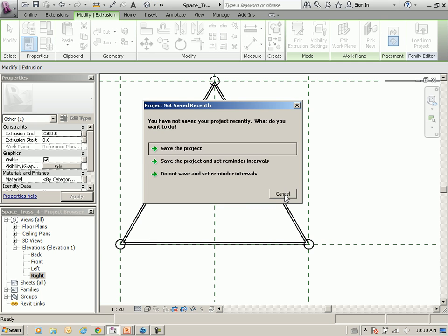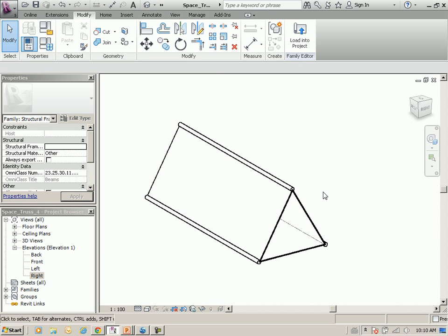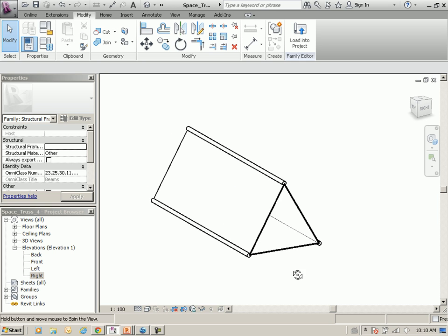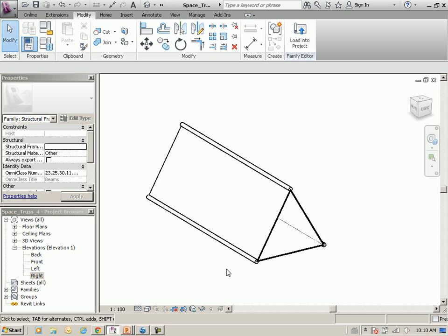But you can see here in the 3D that the webbing is solid. There's nothing taken out of it yet. I tried also with actual elements, and if you look at the K series bar joist, that's exactly what they've done: they made a special family that just adds in the little web pieces. But I'm finding that on angles especially, it's extremely difficult to work with the planes. So this is a little bit more of an accessible option.